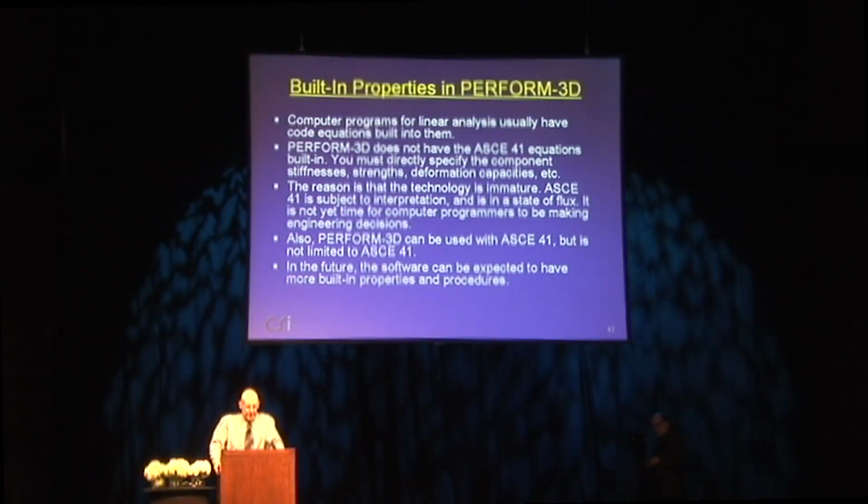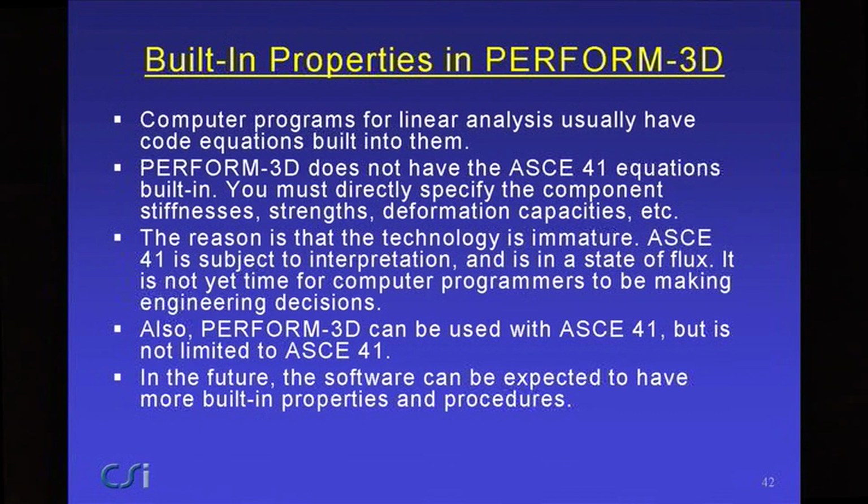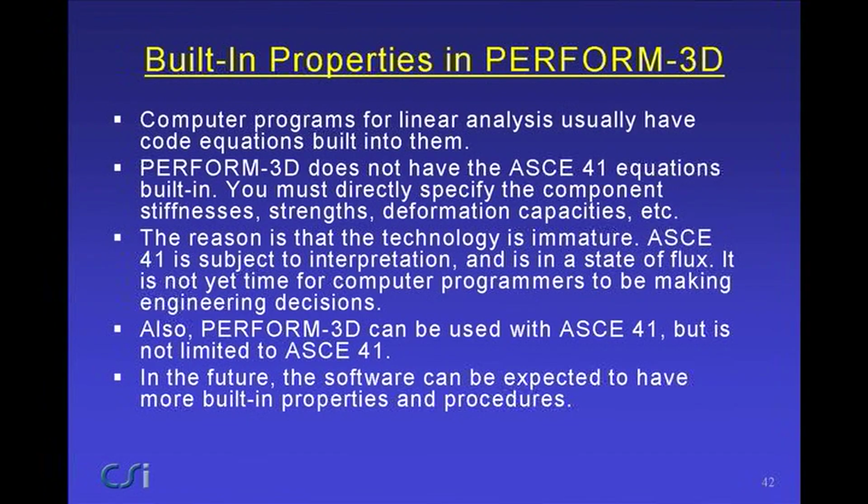Perform 3D does not have many built-in properties. When you look at computer programs for linear analysis, they've usually got the code equations built into them. The early computer programs didn't, but the new ones obviously do, and they're not much use if they don't have code equations built into them. It's not yet time, I think, for computer programmers to be making engineering decisions by building these types of things into a nonlinear analysis program, and in Perform 3D we haven't. In the future you can expect more built-in properties and procedures, but that's down the line a little bit.